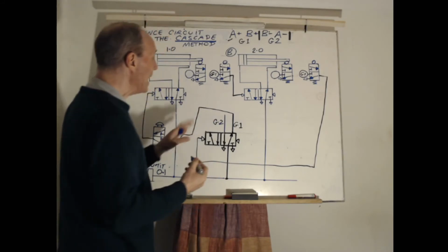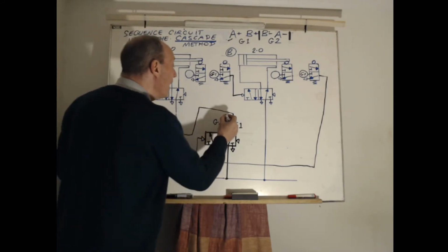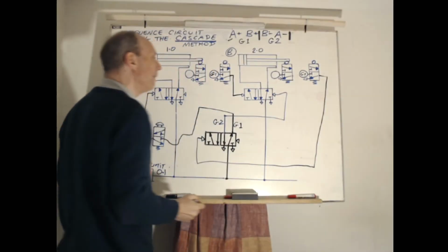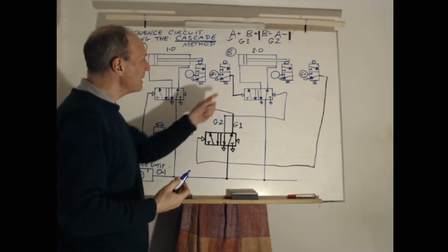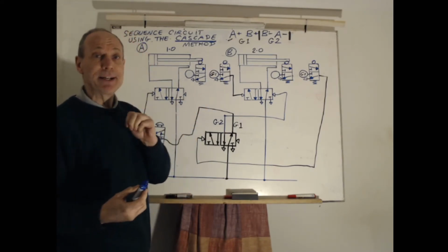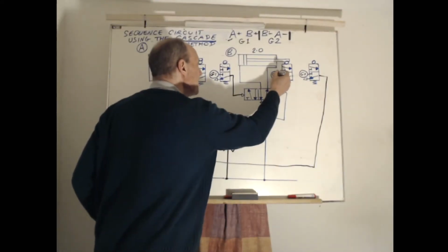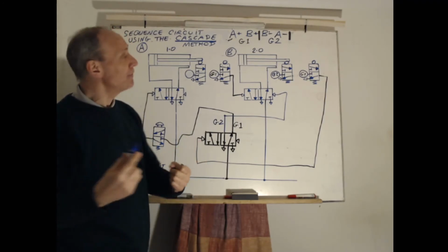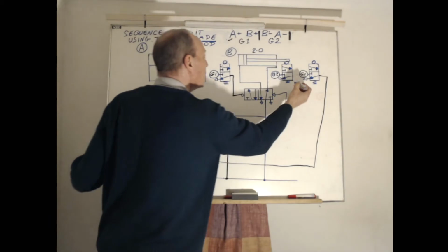So G2 air, which is now online and now present, is going to supply this valve to push it back, so B goes to B minus, and it will go to B minus because this G1 air is dead, the trap signal has gone. It goes back and I'm going to put a G2 there because G2 is now live. It goes back into the negative stroke, and when it goes to the negative stroke it can then operate the next stage, which is A minus.